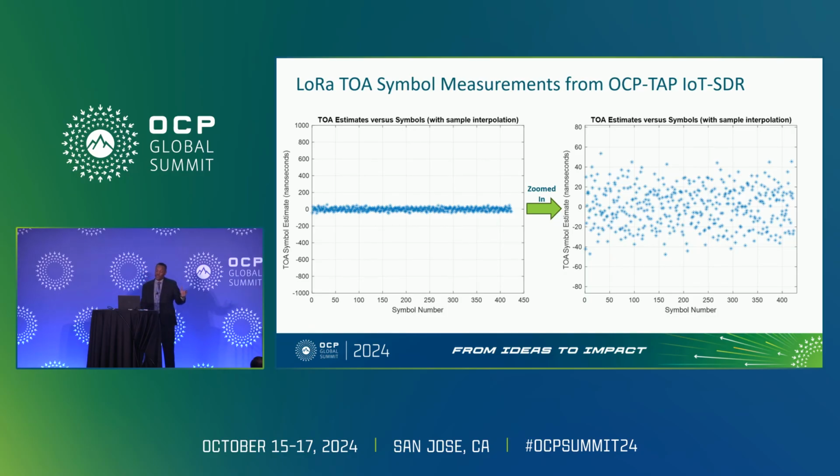Now, that was for time of departure. Time of arrival is on the other side, where I've actually gone across in terms of transmitting from one software-defined radio to the next. In this case, I wanted to emphasize and show the TOAs associated with that. I zoomed in real quick just to let you know you're getting 20 nanoseconds in terms of the actual error itself.